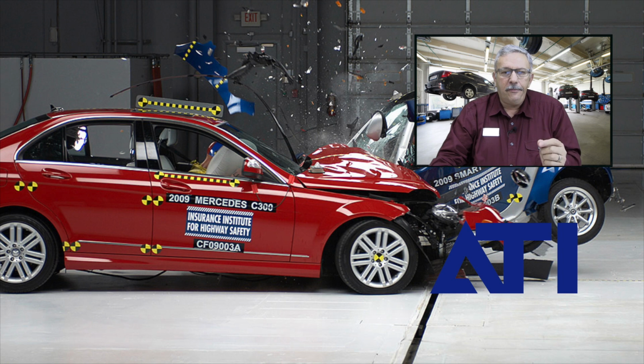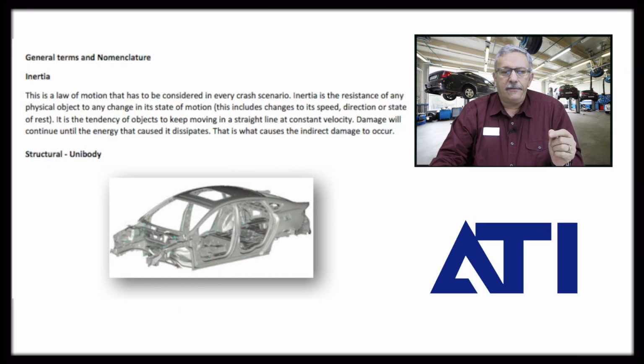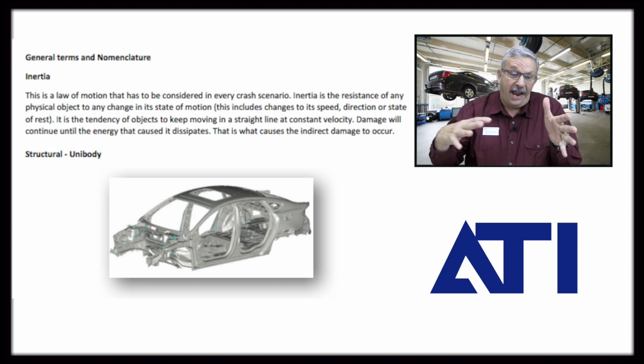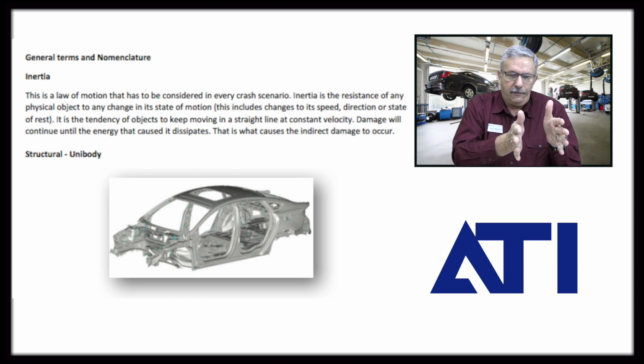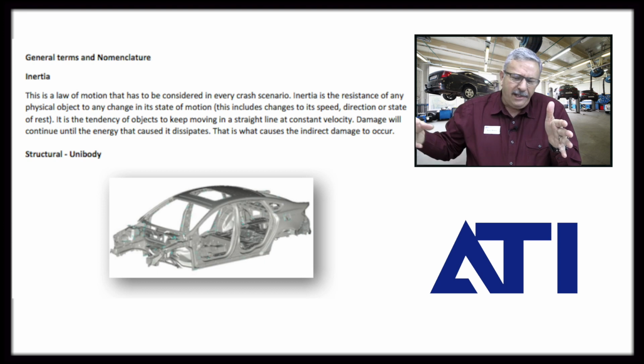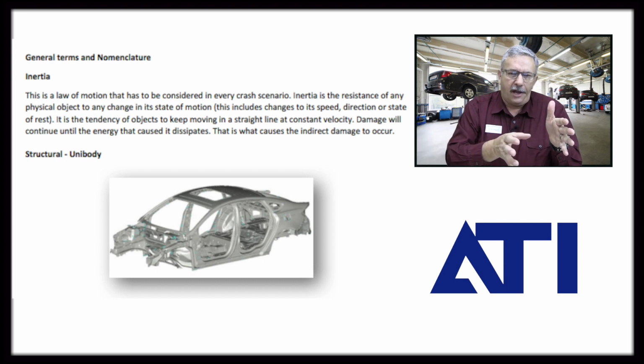So for the first term, inertia, we will have a very detailed video from the Insurance Institute for Highway Safety, which goes through various crash tests so that it illustrates how the parts within the vehicle actually move. Because when the vehicle stops, and the bumper system stops, the motor and transmission, which generally are transverse, will continue to move forward. Everything that's connected to them will also try to move forward.